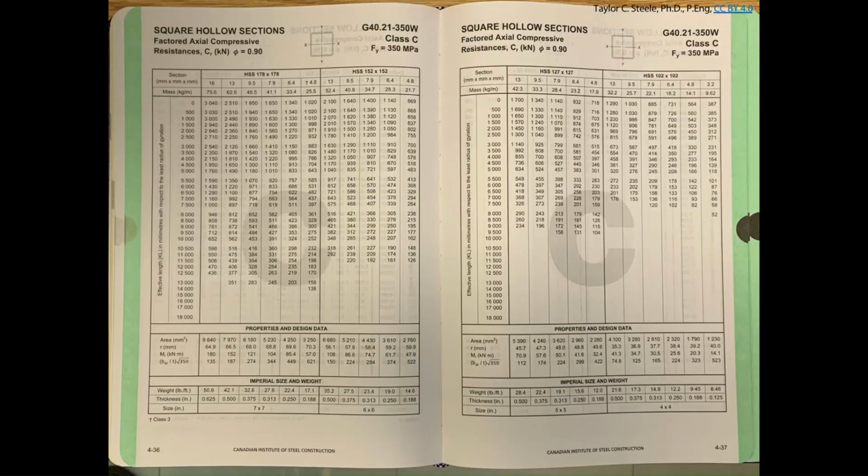If you want to be conservative and you say, oh, I'm going to specify class H, but I'm going to get class H, you can use class C. But if you specify class H, design it for class H, but get class C, then you're in trouble because the strength is 25% smaller depending on what the effective length of that section might have been. Okay, so for these shapes, you have to look at the watermarks to make sure you're selecting from the right classification and grade of HSS steel. Otherwise, you can get yourself in trouble, and that's why they're watermarked in the background.